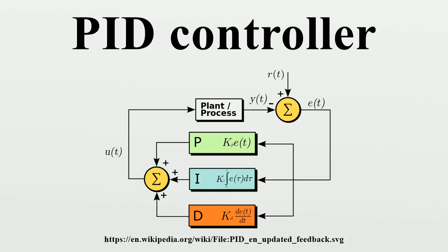is approaching zero. Finally, integral action adds a third term, using the accumulated position error in the past to detect whether the position of the mechanical arm is settling out too low or too high and to set the electrical current in relation not only to the error but also the time for which it has persisted. Over time the steps accumulate and add up dependent on past errors. This is the discrete time equivalent to integration.